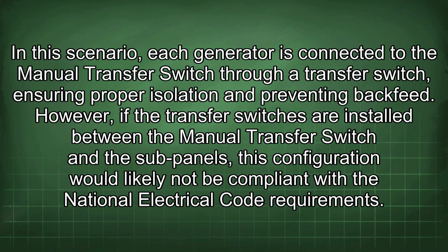In this scenario, each generator is connected to the manual transfer switch through a transfer switch, ensuring proper isolation and preventing backfeed. However, if the transfer switches are installed between the manual transfer switch and the sub-panels, this configuration would likely not be compliant with the National Electrical Code requirements.